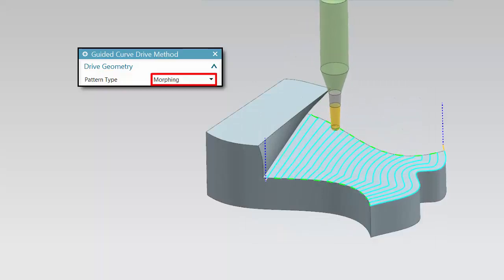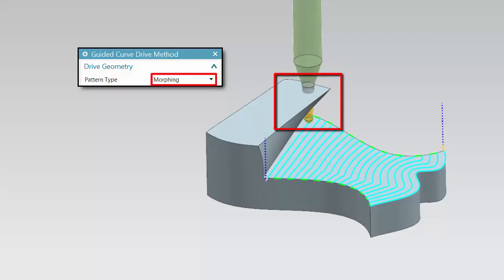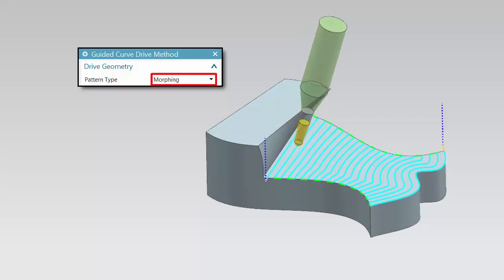For variable guiding curves operations, if the tool cannot reach the specified curve due to a double contact condition, the system will generate a guide curve following the double contact trace. Although portions of the tool may show a collision while working on the pattern, since the operation has the tilt tool axis embedded, the final path is collision-free with maximum coverage. Tilt tool axis also provides smoothing of the tool axis behavior based on the machine characteristics and allows limiting the tool orientation to the swiveling axis limits.